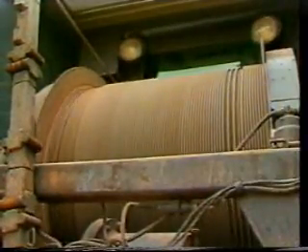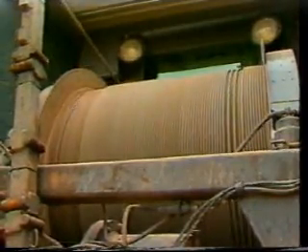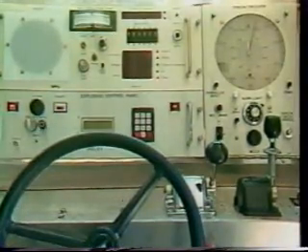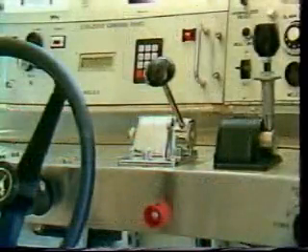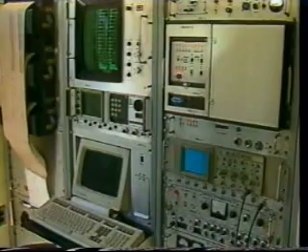The winch mechanism is used to lower and raise the cable and attached logging or sampling tools into the wellbore. A winch control panel measures the amount of tension on the cable and operates the winch at optimum speeds for various logging tools. Also, the tools can be positioned at precise depths for necessary tests and measurements.